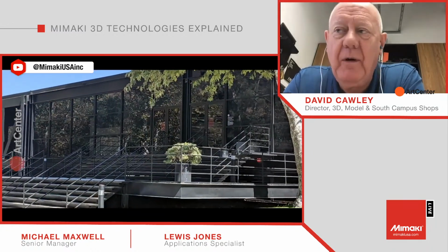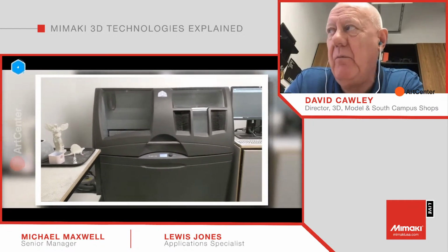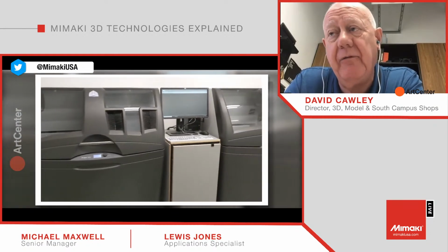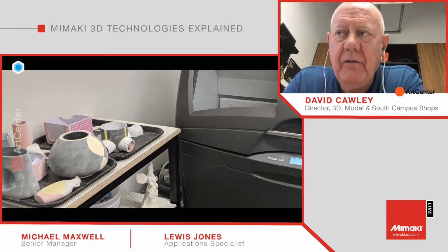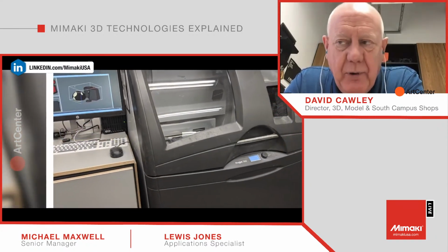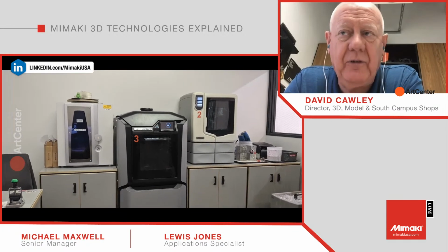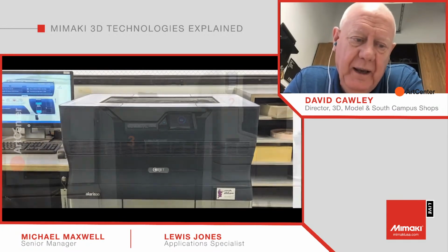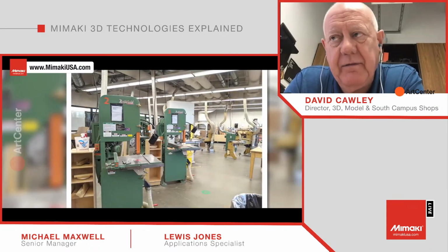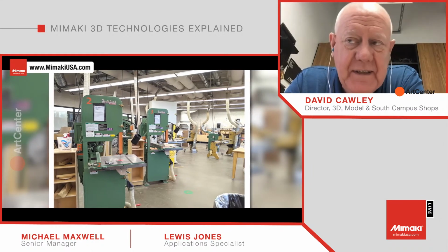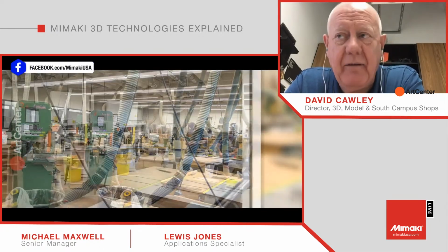And again, the thing has always been, okay, let's look at real products. If we're looking to do manufacturing with 3D printing, then we have to look at what those products are made from. If it's ABS plastic, which is a very common injection mold material, the idea is, okay, if we're going to use a 3D printer to mimic that, we're going to need those material properties from that printer to be very close to the injection molded part, so that we can use that to manufacture as well as prototype. And I think that's one of the areas where materials play such a big role in the ability for 3D printers to actually get into manufacturing.